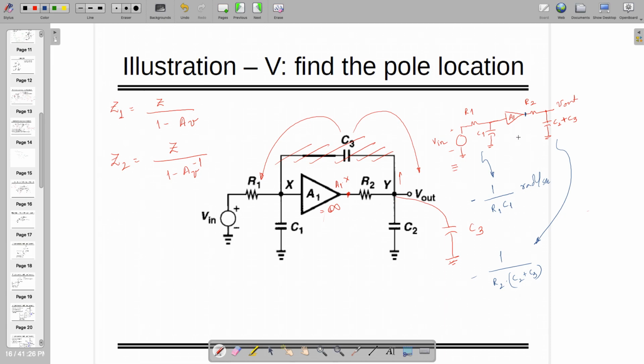Notably, at this point, looking into this, it's infinite. So it's low impedance. So there is a path with respect to ground, so it's not going to load inside, right? So effectively, you are going to see only R2. And same for here. So when you are going to short this, it's only R1. We are going to practice this time constant technique more when we are going to introduce a transistor. Okay, so this is all about Miller theorem and its usage for different illustrations, so that you can use it.